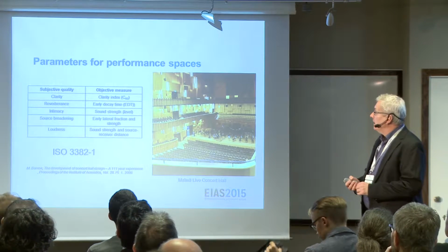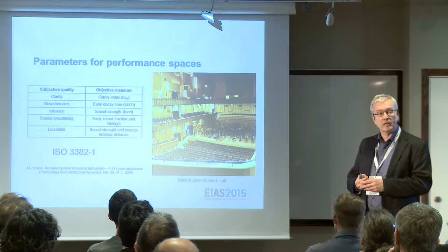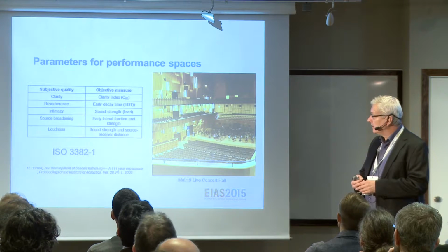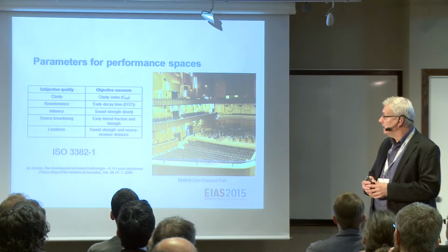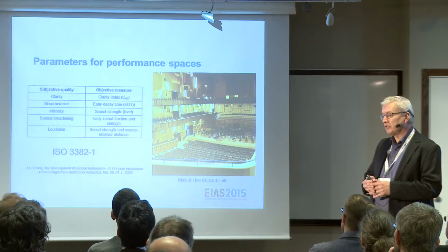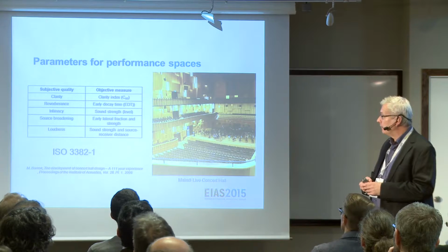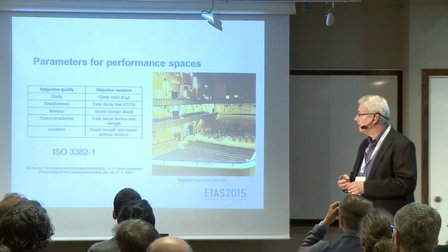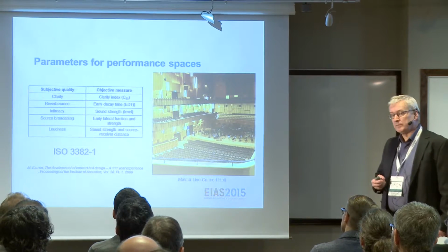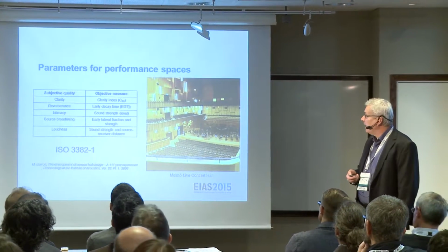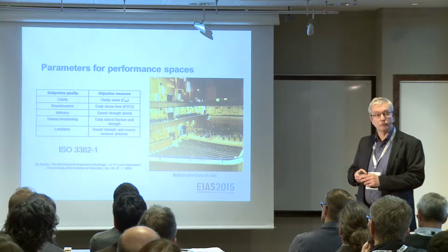There is no doubt that if you try to characterize a concert hall, then we need several quality aspects. Those are from a paper by Barron, and he states that you need at least 7 different measures to characterize a concert hall, related to clarity, reverberance, intimacy, source broadening, and loudness. I guess he especially emphasized loudness. And all these measures are also quite well specified in the ISO standard 3382 part 1.